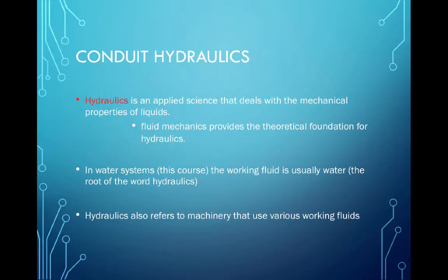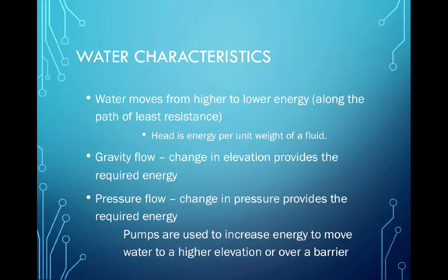Hydraulics is an applied science that deals with mechanical properties of fluids, and fluid mechanics is the theoretical foundation for everything today in this lesson. And in water systems, the working fluid is water. Some important characteristics is that water will move from higher to lower energy along the path of least resistance. And the term we had from fluid mechanics called head is the energy per unit weight of a fluid, and it represents the energy at a location in a fluid system, or in a water system, if you will,